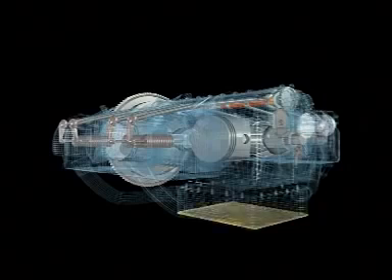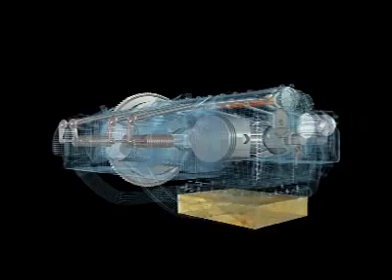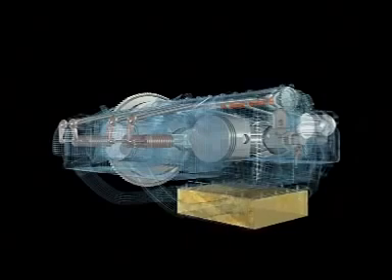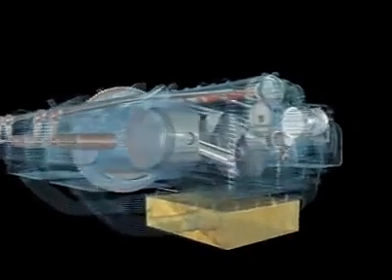The journey of the oil starts at the reservoir in the bottom or sump of an engine. It's drawn up towards the oil pump, passes through the pump and on into the filter. The oil, now under pressure, fills the filter before entering a maze of passageways, known as oil galleries, from where it's directed to the main engine bearings.